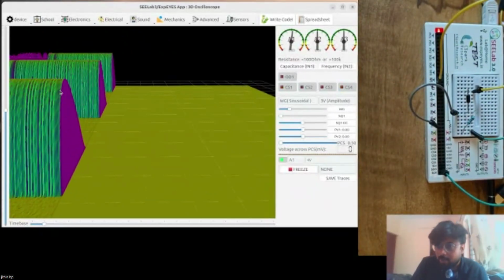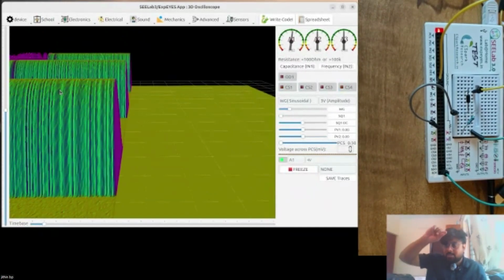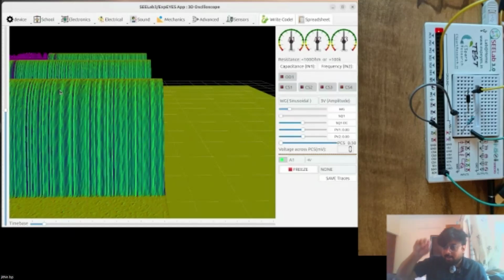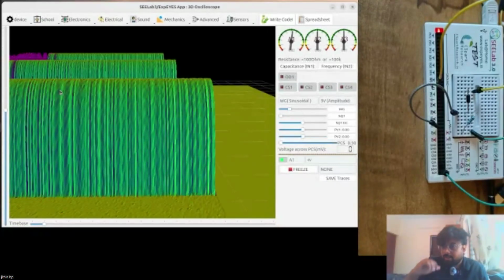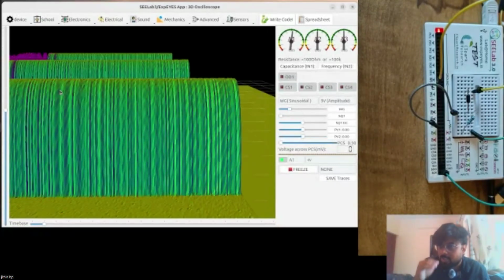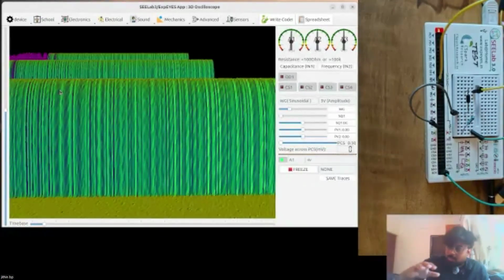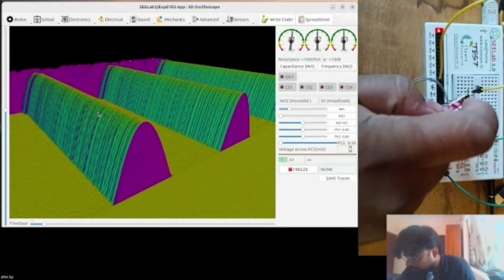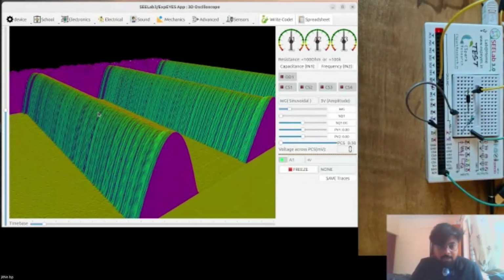You have done the half wave rectifier experiment. Have you all done? Yes. So there, what happens is the rectified output is not overlapping the initial one. There is a small gap, and that gap comes because of the forward voltage. The diode needs a minimum of 0.5, 0.6 volts before it starts conducting. So that is subtracted. So if you give 3 volts, you only get something like 2.4 volt height. So here in this view, if I simply heat this diode, did you see that small bump?